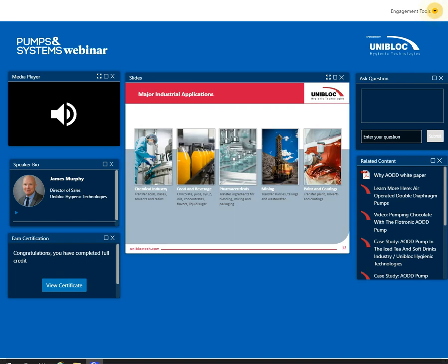So let's talk about some applications out in the market. The chemical industry is obviously a big one. We've all been in plants where we've seen diaphragm pumps, typically constructed out of polypropylene, PVDF, maybe PTFE. These are really nice utilitarian applications where they're transferring some type of chemical through a filter or through the process within the plant. So they're just a transfer pump in this case.